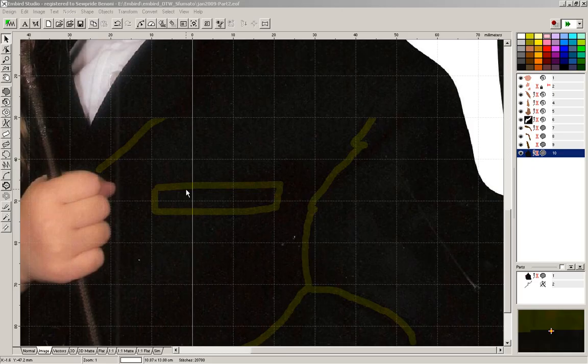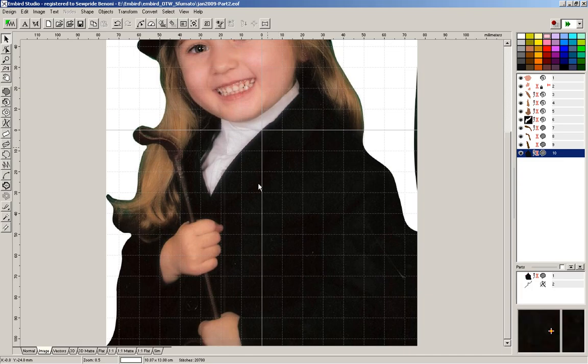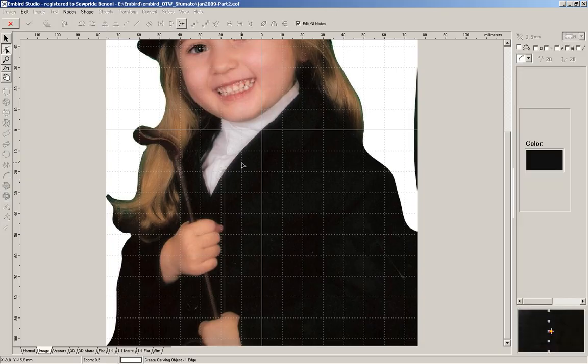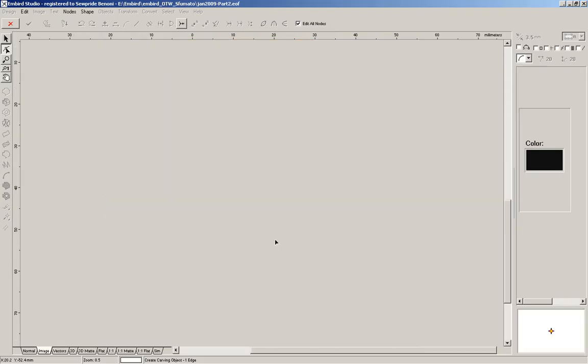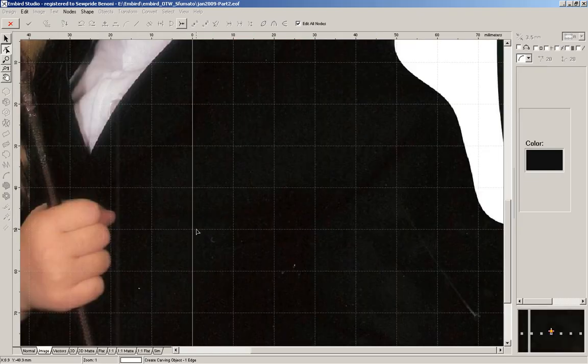Right. I've already done the top section. I've already done this section at the top here. And now I need to put that pocket portion in, and I'm going to use the embossing tool on the left hand side. You see the screen has changed, it's fine. So right, let's go down and see if we can put that emboss section in there.